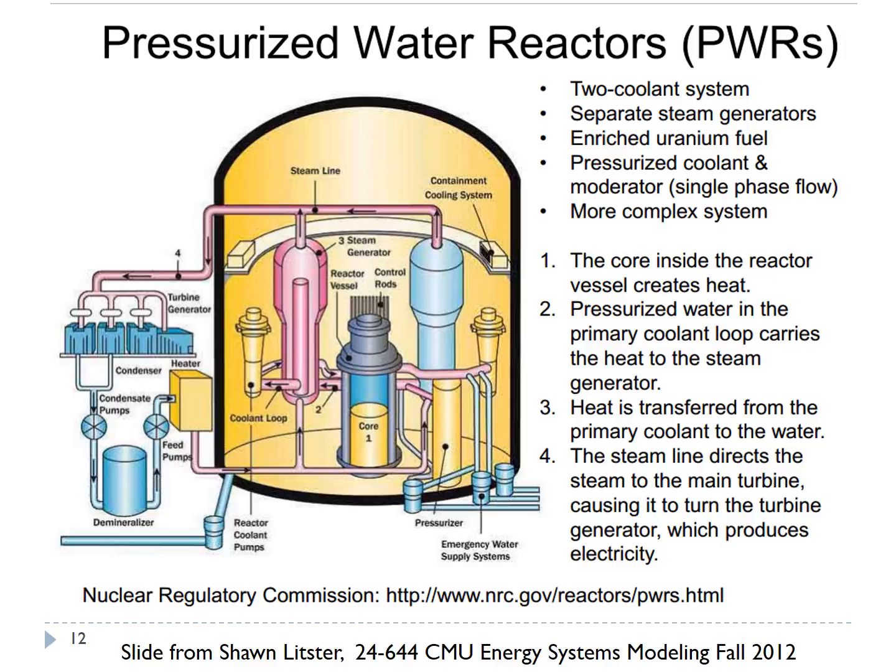So in this case, in the core itself, you have high pressure water that doesn't boil. And that's going to be heat exchanged. So here in the core, you have one fluid, that's going to be heat exchanged with your working fluid, which would then go through the turbines to generate electricity. And then you have a condenser and it's pumped back up before it goes into the system. Key thing here is that there's no boiling occurring in the core. But you can see we have a lot more equipment here, so it's more complex.